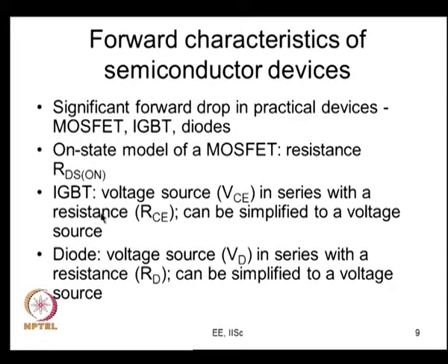If it is an IGBT, the forward characteristics can be modeled by considering the IGBT to be a voltage source VCE in series with a resistance RCE. So, this can be a model for your IGBTs, but this can be simplified.